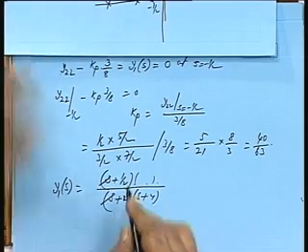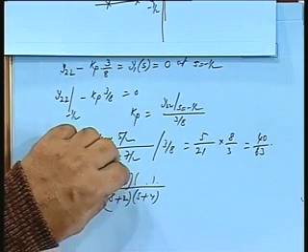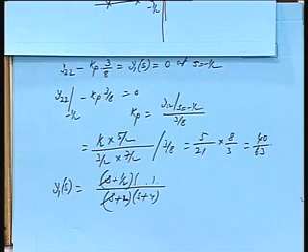Okay. So, after you have realized a 0 at a particular location, how to realize the network element, how to get rid of it? Whenever there is a 0, how do you remove that 0? Invert it, create a pole, make partial fraction and remove that, is it not?